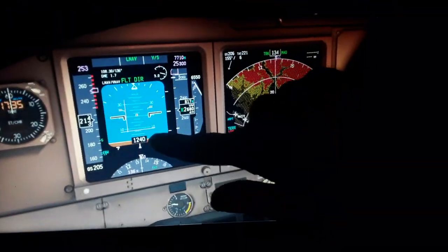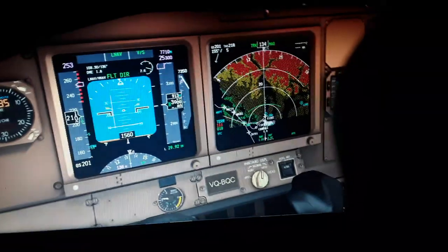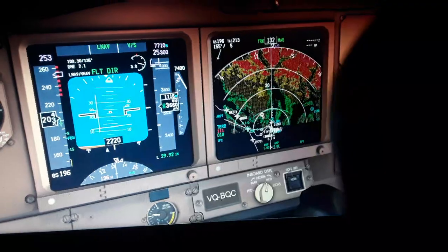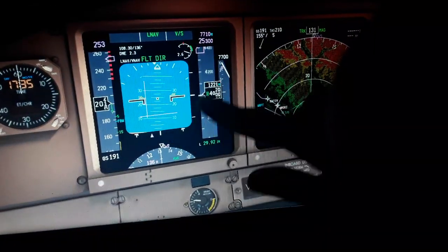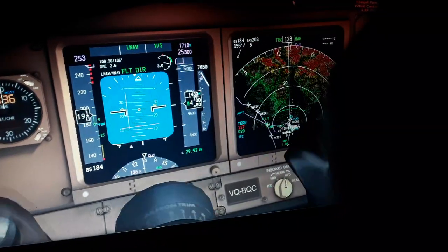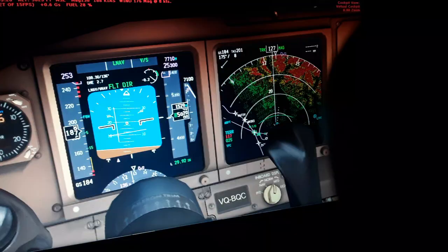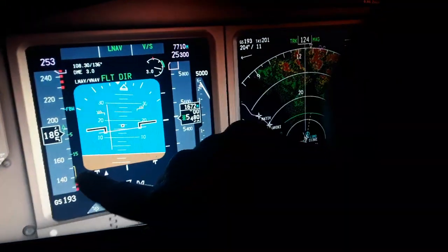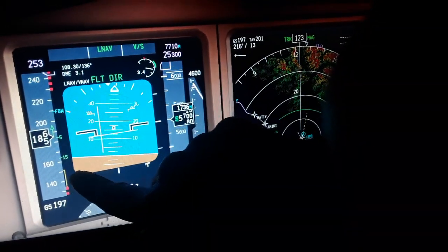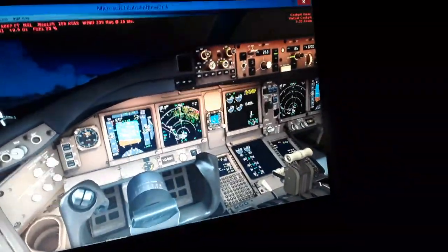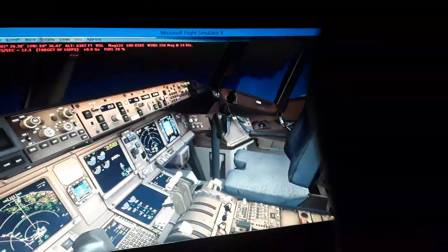You can see we are 1000 feet, 200 above the ground level, about 3000 feet above sea level. Now we are 2500 feet above the ground, but 4000 above the sea. We climb to 7000 feet, gear speed 190 knots. We decrease the rate of climb. We have the flaps limit, and this is the stall speed warning, 145. We stall at about 130 knots. We keep climbing. With this flap setting, we stall at about 130.